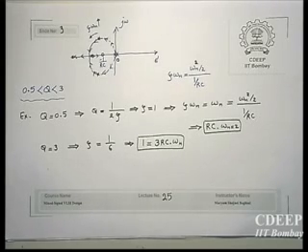But practically, values close to Q equal to 0.5 up to Q equal to 1 are okay. I mean, I told you Q equal to 3, but it's not always used. So therefore, what are now the considerations in a charge pump-based PLL? Similar to the first order filter that we had before, here also we have some trade-offs.